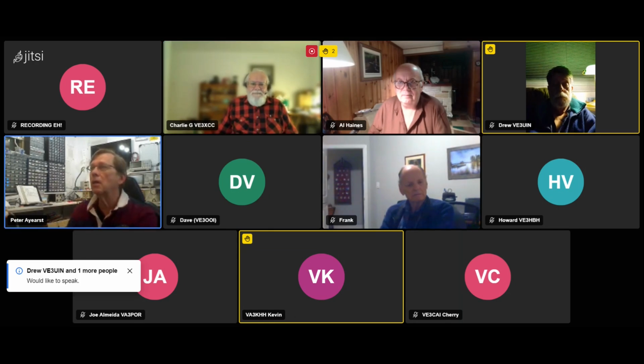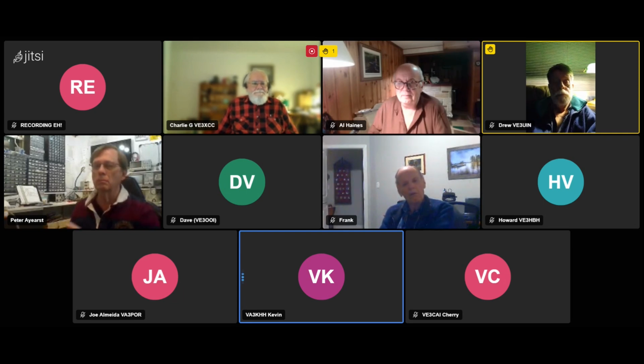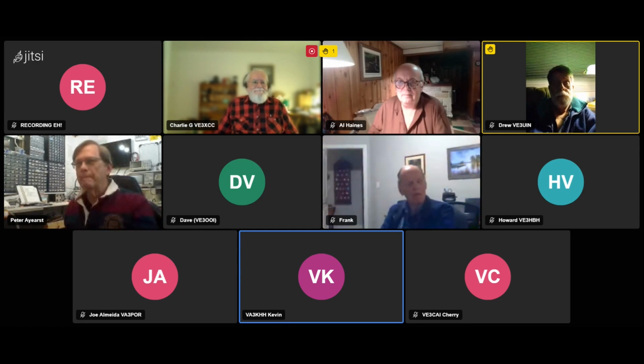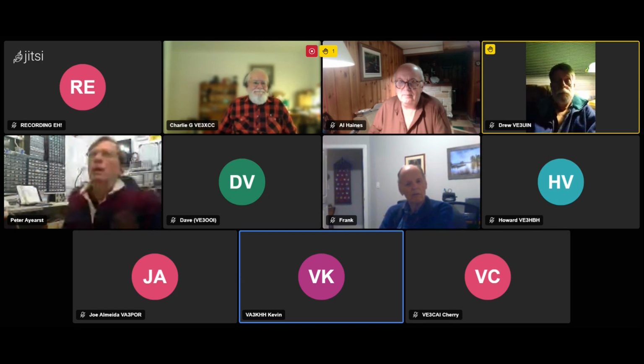Okay, thanks. Kevin. Hi. Yeah. I was just going to say, as far as I know, the skin depth is inversely proportional to the frequency, so the depth goes down as 1/f. So that makes sense. Charlie's point, it's frequency, and even to the point about tubes, at Bruce, the power conductors coming out of the main generator are like 2 foot diameter copper tubes. They're not solid wires or bus bars for that reason.